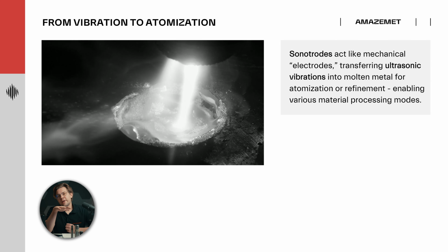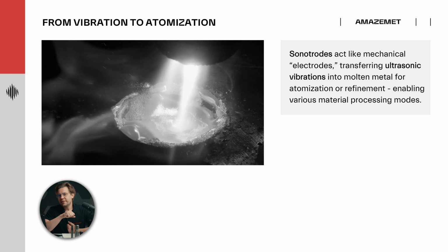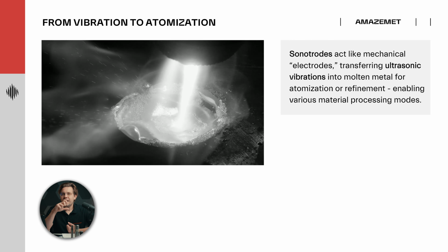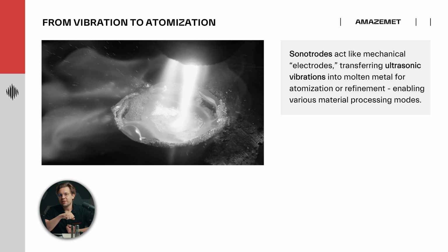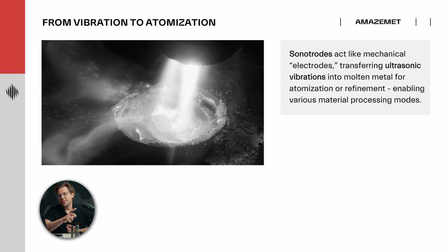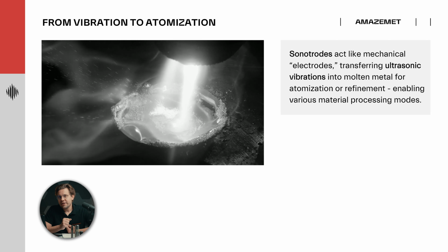A melt pool agitated with ultrasounds, powder being sprayed, but how are the elements that actually transfer the ultrasounds into the melt composed? What is the nature of those elements, how do they operate, and what are the different types of Sonotrodes? Here we have several different types of Sonotrodes. I would like today to explain how they are used, how they are composed, and what are their pros and cons.